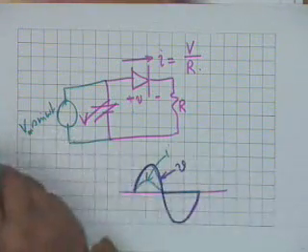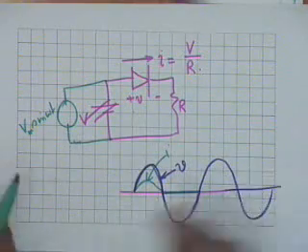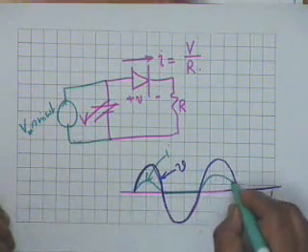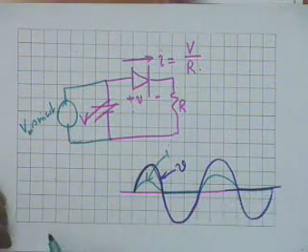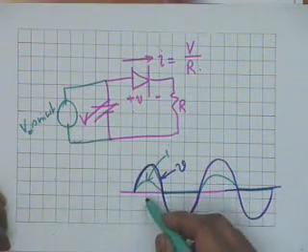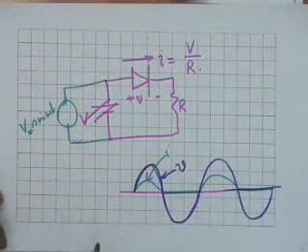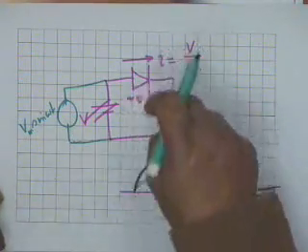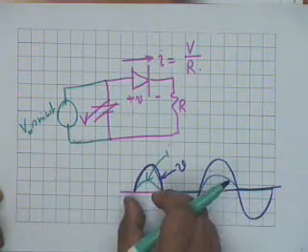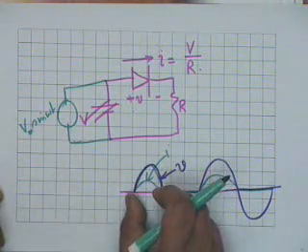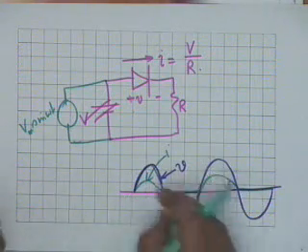And for the next cycle again, the current shall be positive, current shall flow, and then the current shall not flow. So, if you have an alternating voltage like this, Vm sin omega t, then the current in this circuit is pulsating. It consists of half sinusoid pulses only during the positive half of the voltage.